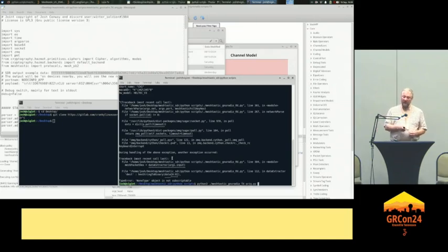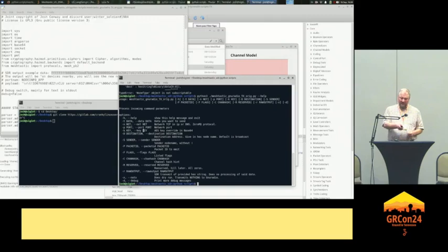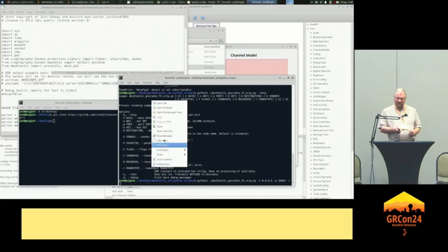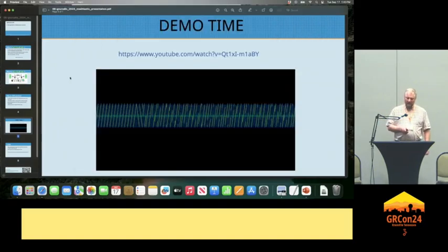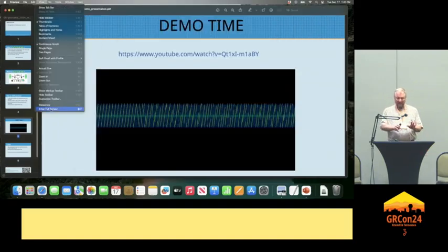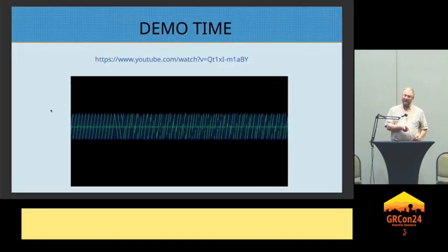a GNU radio, the transmit script here, as we see here. And we can just send the raw data directly into it, and it will transmit out over the air, over the HackRF. And again, this works for any front end, so HackRF, BladeRF, USRP, any other transmit compatible is perfectly acceptable. And I think this is the end of the video here. Oops. There. Awesome. And if you keep it on the screen, this is actually what was shown here just a moment ago, but this is what a LoRa transmission looks like as well, with all of the symbols like that.